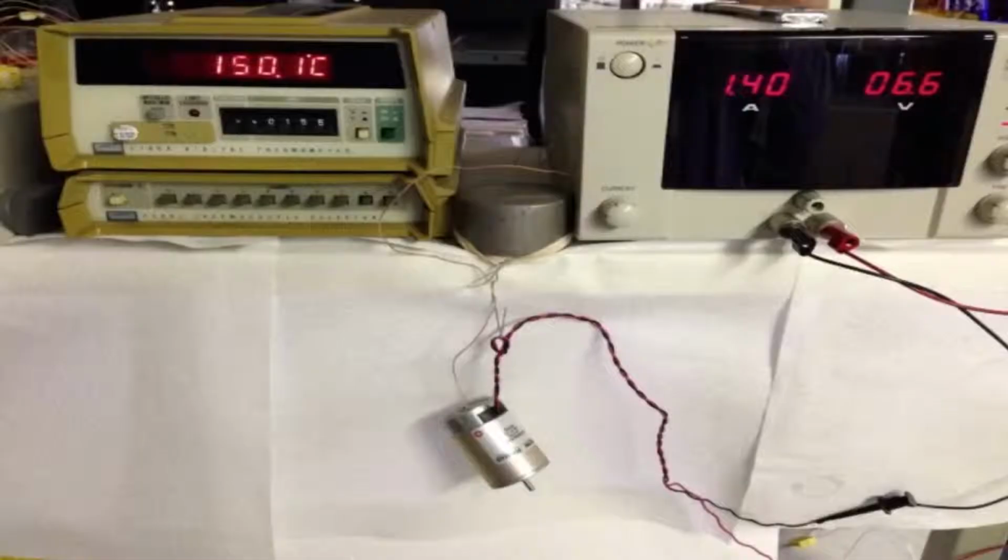Pittman motor data for the 6000, 8000, 9000, and 14000 series is based on tests where our motors are suspended by wires in standing air at room temperature, or 25 C. The rotor is locked to prevent rotation. You can see the thermal probe indicates the internal temperature of the armature. This setup minimizes the amount of heat transferred due to contact directly or through a medium.